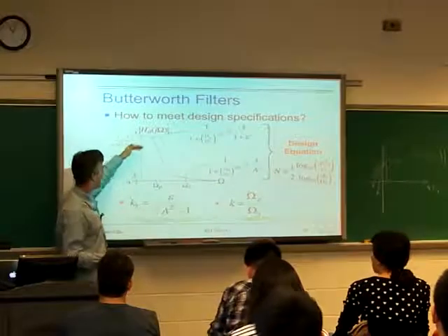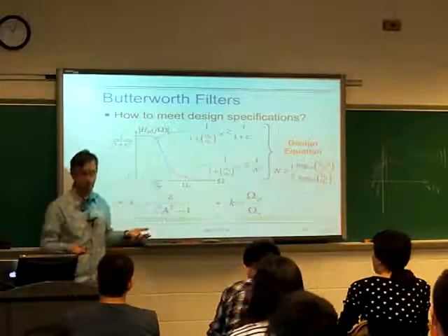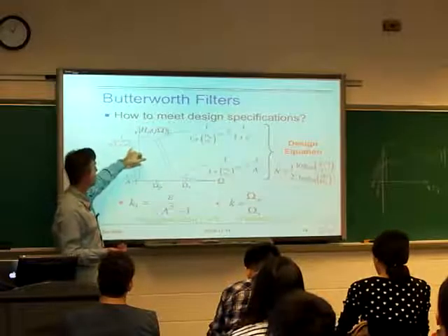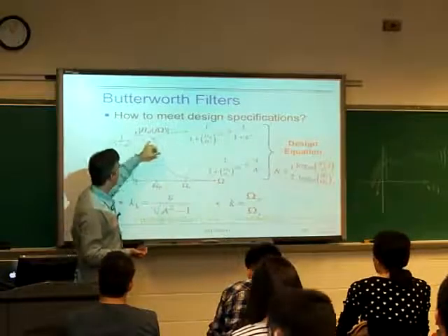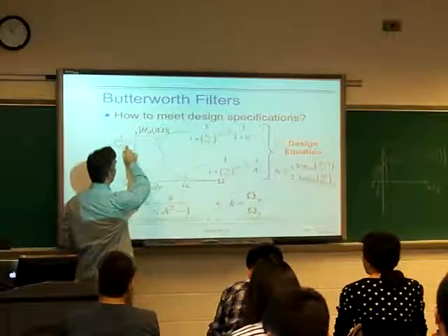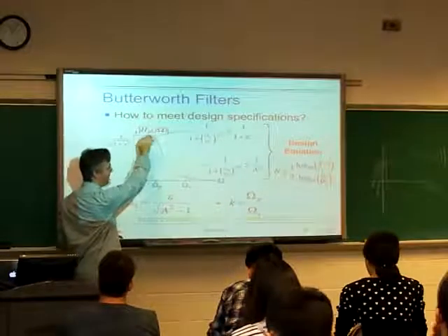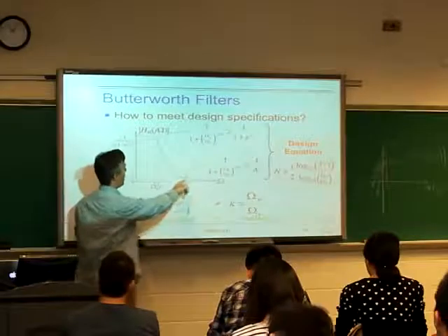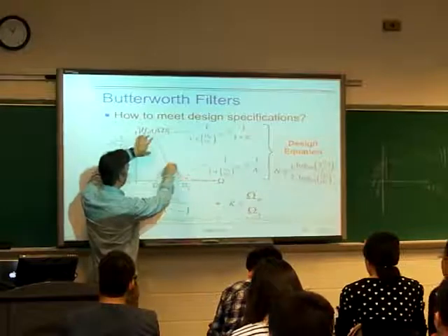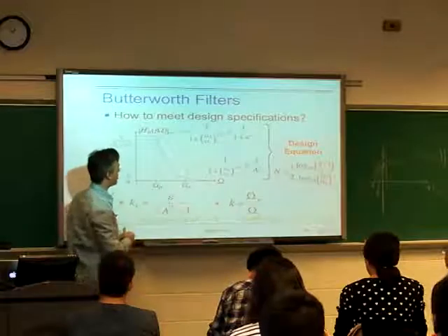The Butterworth filter is defined in terms of the cutoff frequency, the 3 dB point, but maybe we don't care about the 3 dB point. We want some other gain point that we have to achieve, 1 over square root of 1 plus epsilon squared. And so we end up in our classic specification, where we've got a maximum allowable pass band deviation, which is our ripple depth, but there's no ripple here, maybe 1/2 ripple. And the maximum allowable stop band gain. We've got a couple of points here, so we're trying to find the particular Butterworth curve that meets those points.